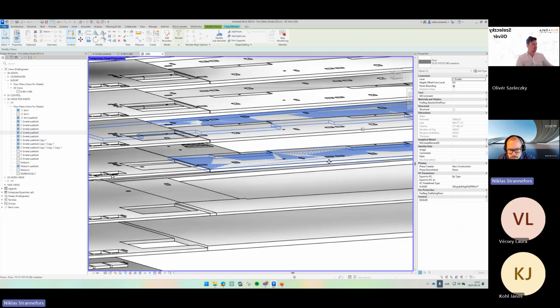Brilliant. The next thing I usually do when I do this is adjust the volume of this slab. As I mentioned, now we can see these reporting parameters. We can't change it because it just reports the total thickness, what we have assigned or what they have assigned. What I usually do is I change the thickness, usually by 2 millimeters.